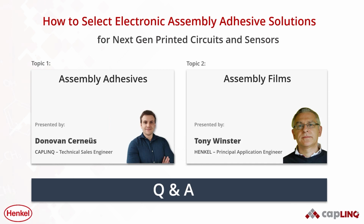Any comments or anything to add, Tony, to that? Well, I agree with you. It's not as easy as with solder, but it is done, particularly with these complicated, expensive modules. If those are assembled and you find that there's one defective component on there, it's well worth going to the effort of heating the whole thing up, removing the component, cleaning up, removing any debris that's around, and fitting a new component, and that's widely done in the industry.